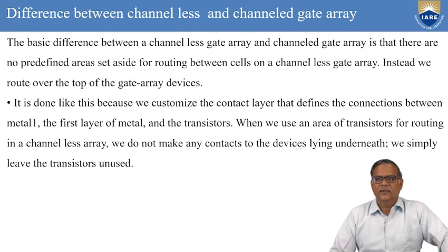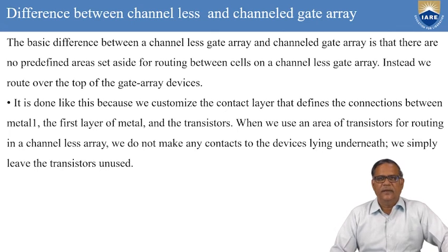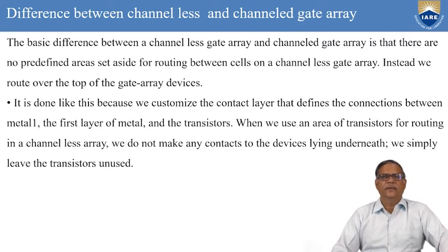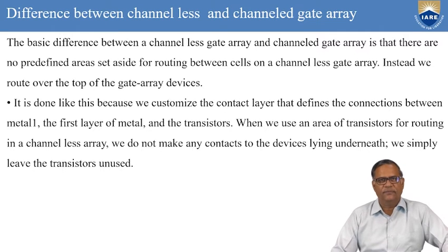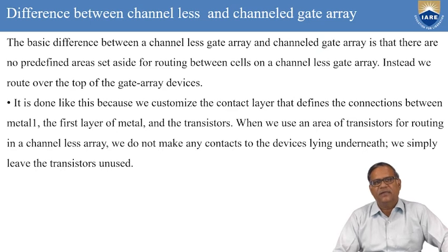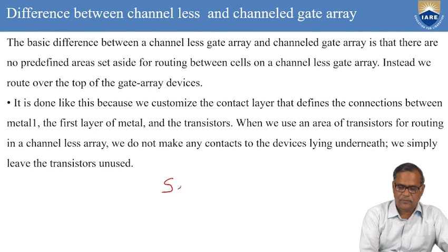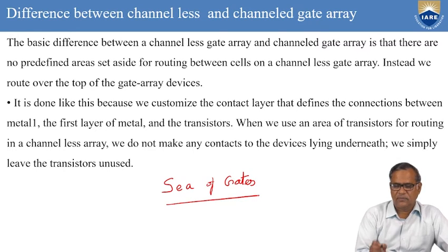So we use the area of transistors for routing in a channelless gate array, but we do not make any contacts to the devices lying underneath. We simply leave the transistors unused. And we get more packing density in channelless gate array, and the channelless gate array is also called sea of gates.